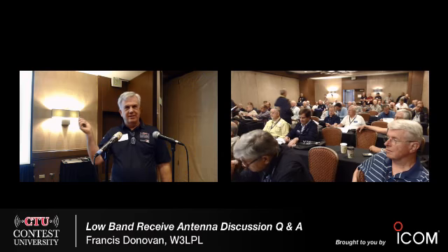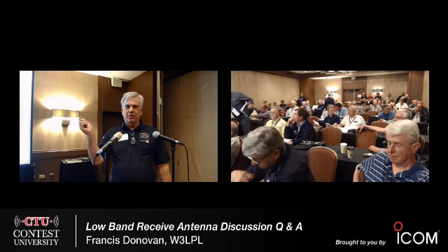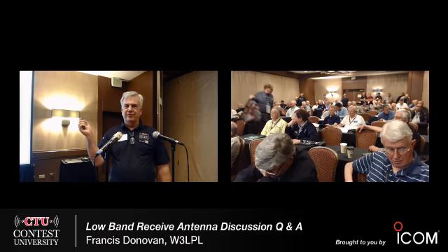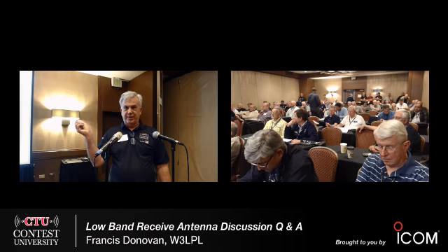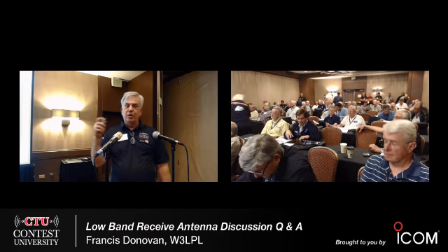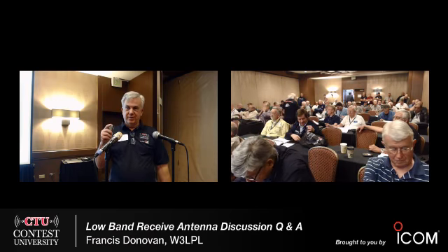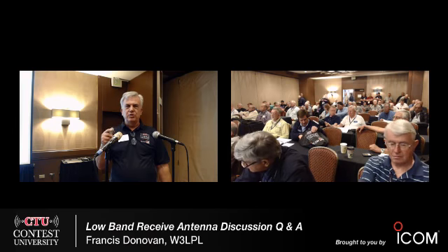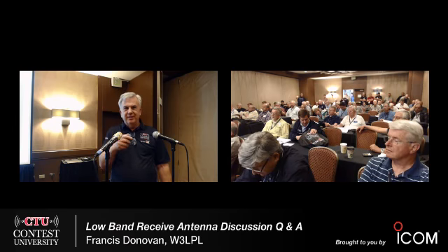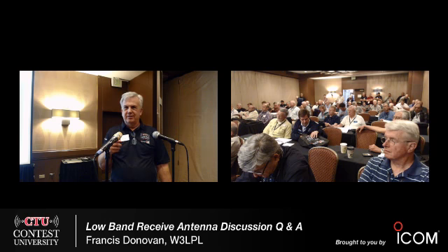But these vertical antennas, not so much, because they all depend on the physical separation of the verticals for their excellent performance. With the high Z antenna, the high Z verticals, you can use their compromised dimensions to get pretty good performance on 2 bands.